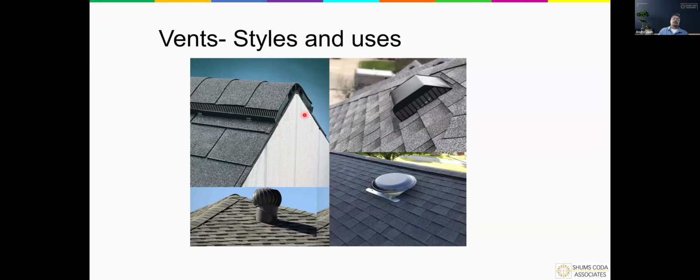And it's one of those other parts to this that's a good reminder that roofs are not a place that are just touched by builders at the front end of construction. They're going to be touched multiple times. And oftentimes during re-roof permits, a lot of ventilation is either added or the style is changed. And that can either adversely affect or it can also help a roof. But that effect does happen repeatedly over the lifetime of the building, and it's something that's more dynamic than just the original design typically.